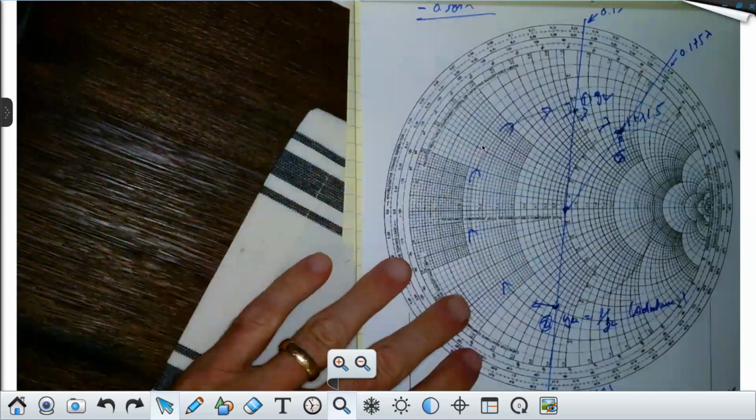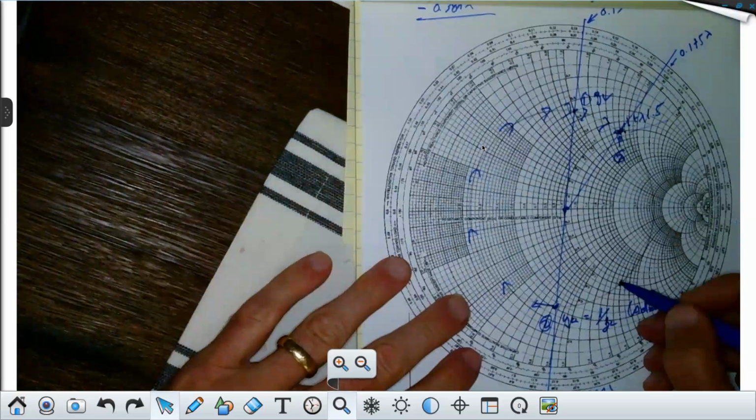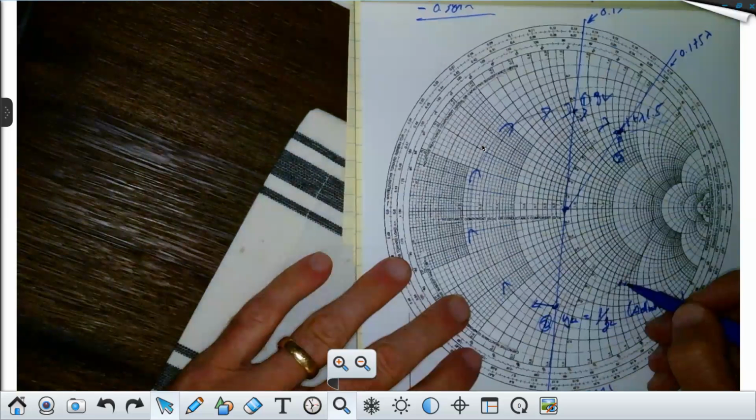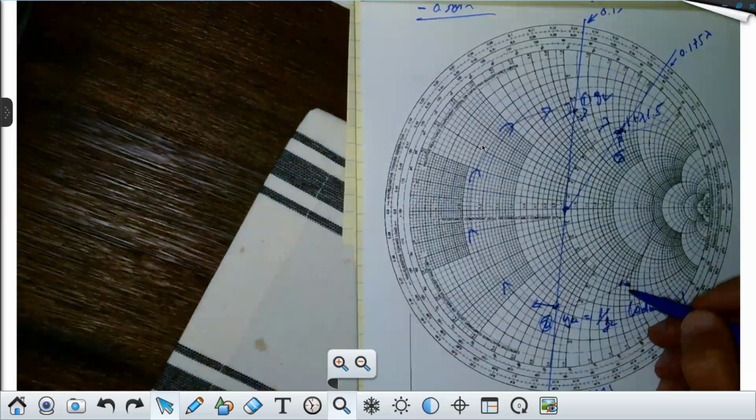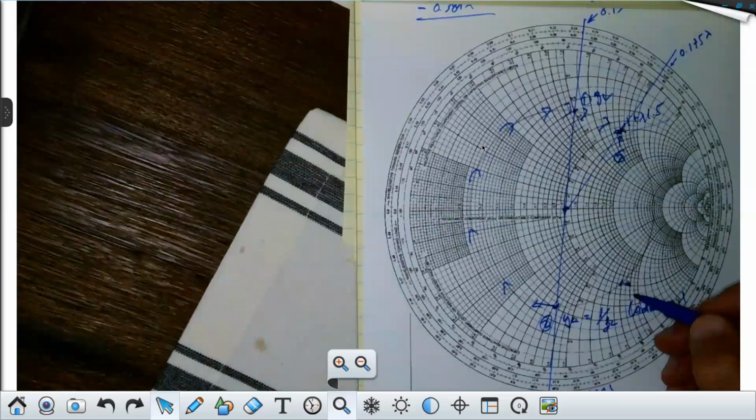That's one point. You know you can go to this point as well, right? And here you're going to have 1 minus J something, correct, class? With me? Show of hands. I know I'm running over, forgive me. So now you would add something in parallel that would have an admittance of positive J, and that would be a capacitor. Capacitors have admittances J omega C.